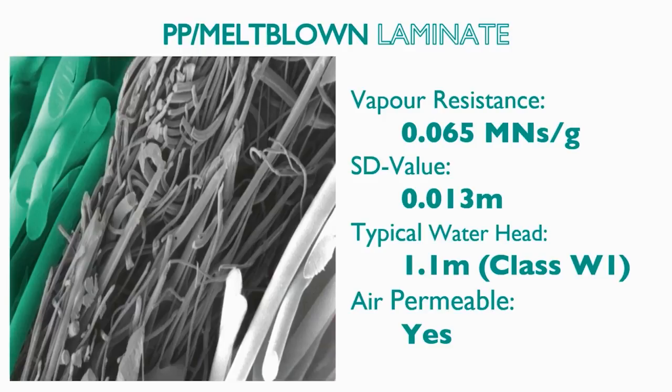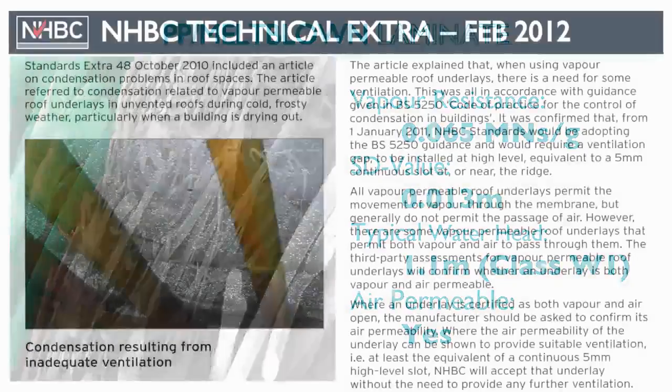Because the membrane is also air permeable, excess moisture loadings are easily accommodated, greatly reducing condensation risks and meaning there are few restrictions on the use of such membranes. Vapour control layers and additional ventilation are typically not required for common roof constructions. We'll now take a look at the implications and benefits of air permeable roofing underlays.